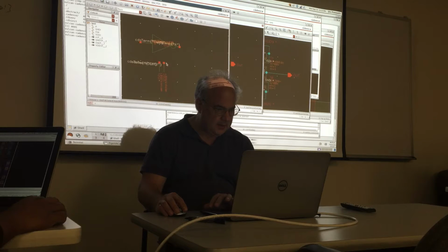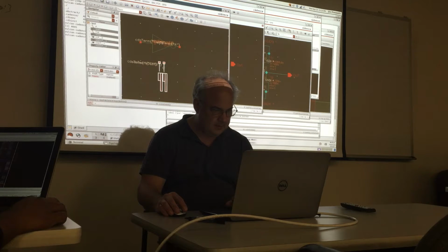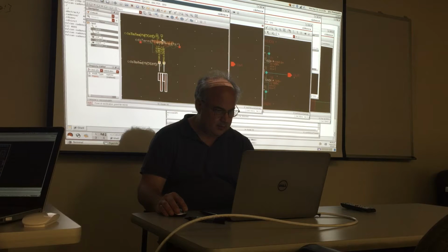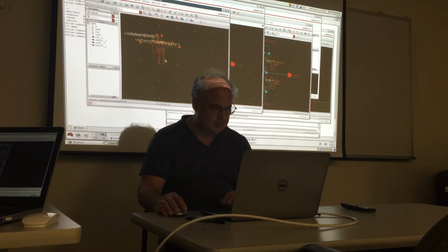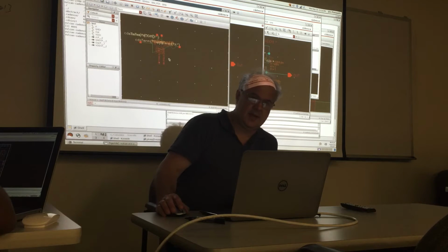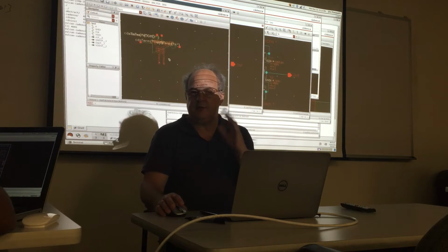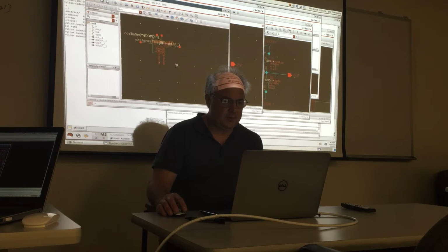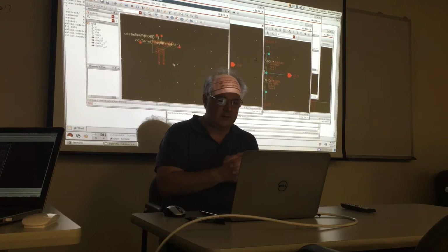Right, now you can actually then move these guys up to where they need to be. And I think you have to select everything. So don't forget that. I usually put them up at the top somewhere. Then you've got to fiddle around with the sizing and stuff. Use mine as examples, okay? But you'll have to do it twice, otherwise you won't get the VDD and ground inherited connections, and you need to have those. You won't wire to them for the most part.